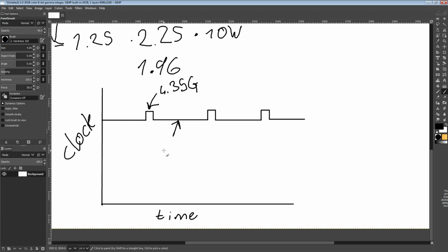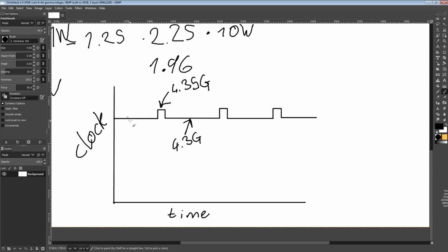And that's 4.3. So if you start doing, say, BCLK overclocking, what you're going to run into is that this stupid little spike of frequency is actually going to crash the chip, even though if you took the average clock speed from here to here, your effective clock speed is like 4.3 something, right? These little nubs of extra clock speed do nothing for performance over a long time scale, but they are really bad for stability.